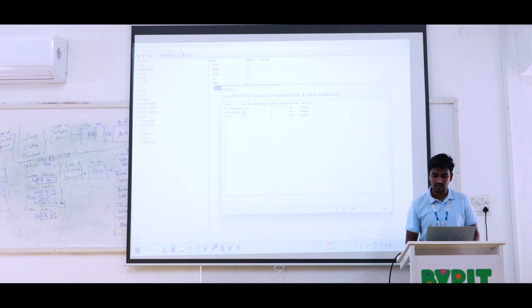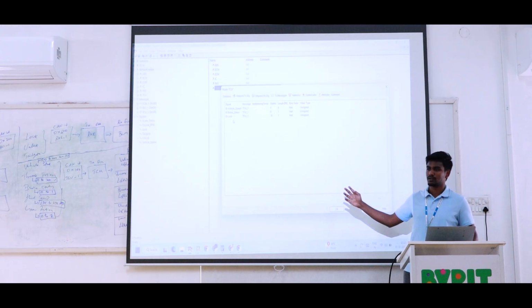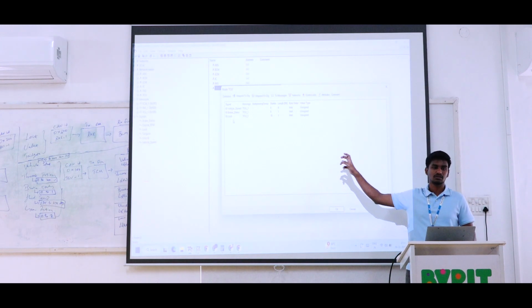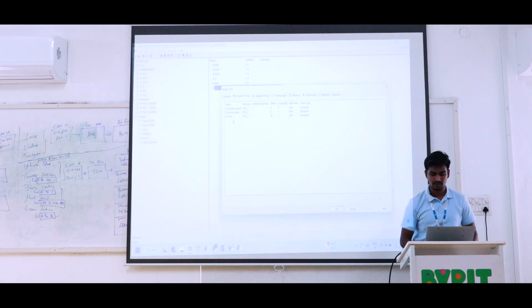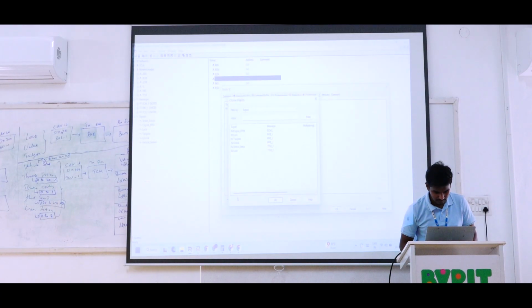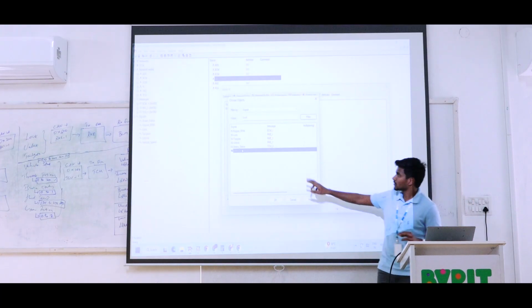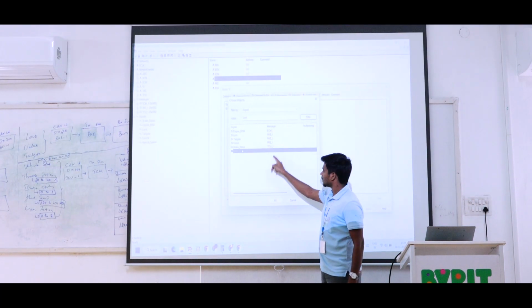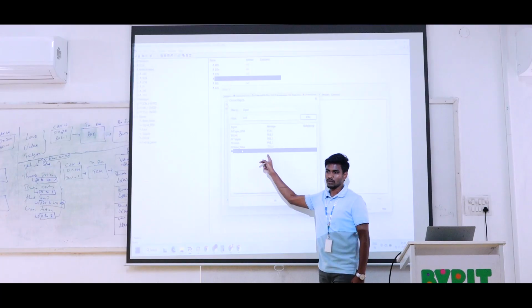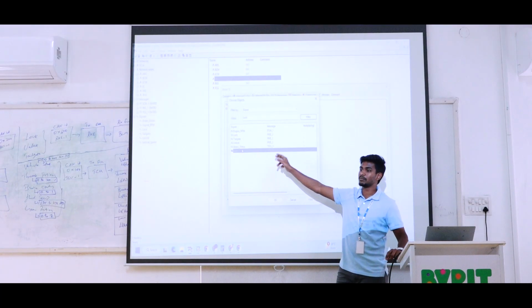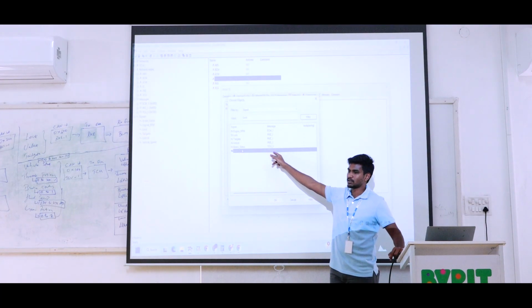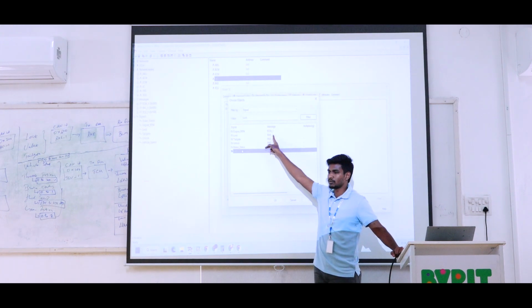Transmitted signals from TCU: vehicle speed, brake status, and then lock. Now we have added the lock. Previously we entered the entire message, so automatically the lock will also be engaged with this. So now we can check it in the IC. The IC can receive the added signal from lock. Here you can see two locks are there, RKU1 and TCU1. So two signal values can be generated for different kinds of messages, each having a different message ID.